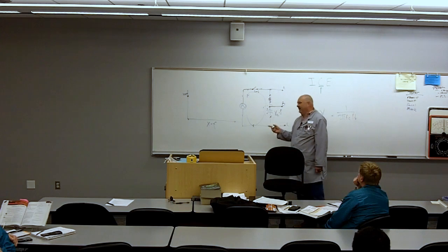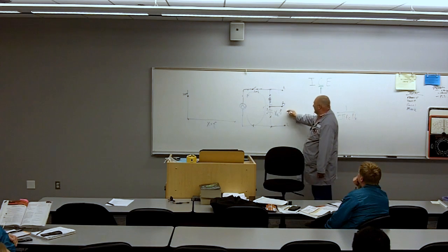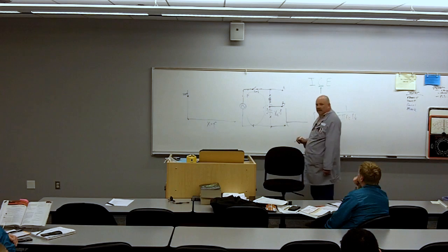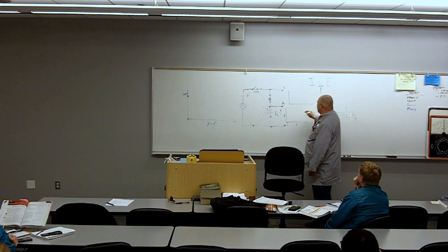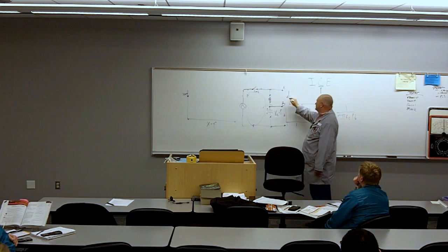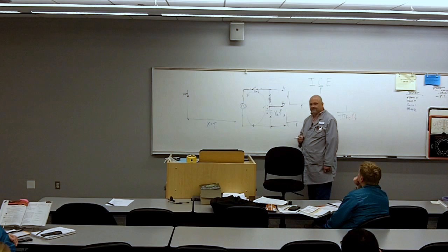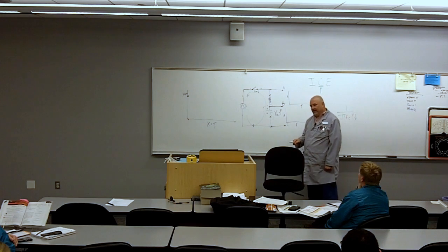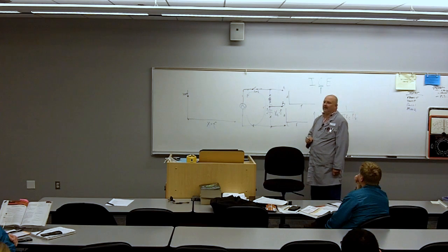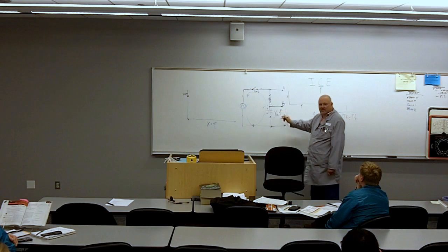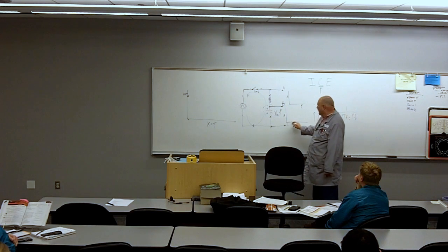So when I put in, let's do a mini XY plot right here. This is frequency, this is amplitude. Let's do the same thing across A and B. This is frequency, this is amplitude. At a low frequency, where am I going to get the biggest voltage drop in this circuit? Across the capacitor, because this has a high value of XC. So how would I plot out at a low frequency AC voltage drop?